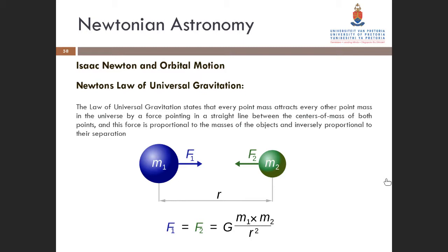If you are in the middle of nowhere, no residential area around you, the ground is literally lifting up by 25 to 27 centimeters when it's high tide and gets pushed down by 25 to 27 centimeters when it's low tide. At your home where you are sitting, that can be between 3 and 7 centimeters. That's a daily occurrence.